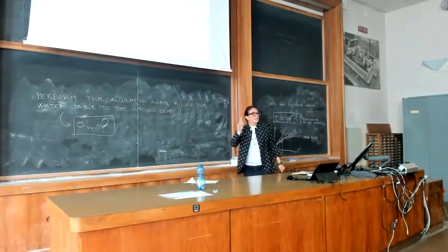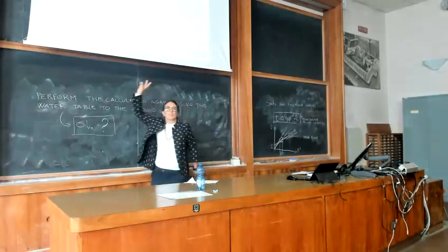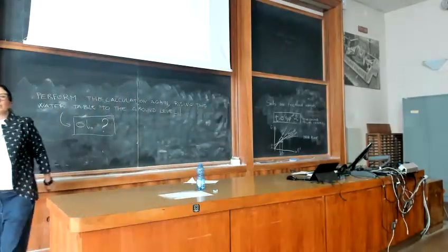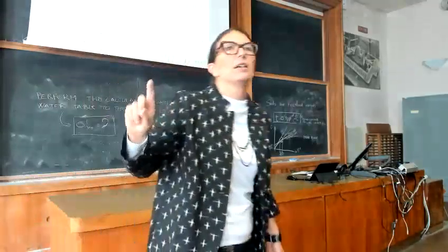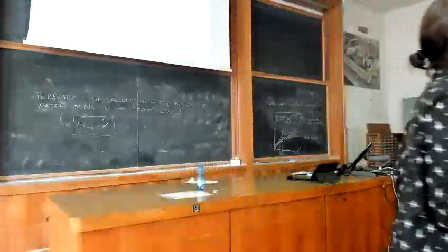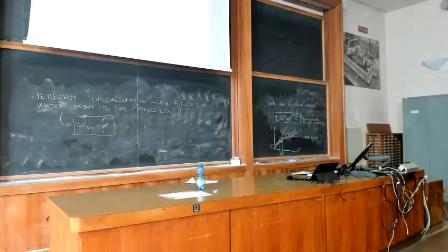As I told you, in 1D everything is simple. In 2D it's not easy to predict pore water pressure when you have two-dimensional flow or 3D. In these cases you can adopt the strategy based on the drawing of flow nets. Do you remember that?